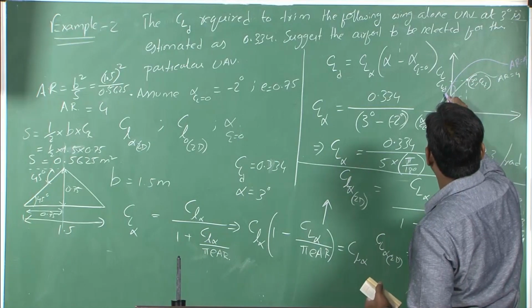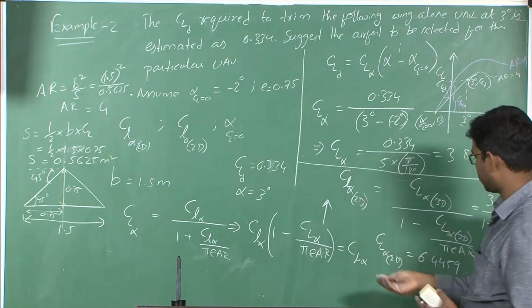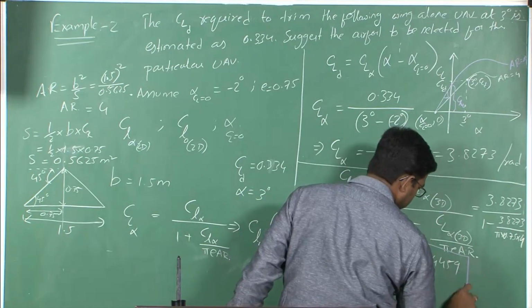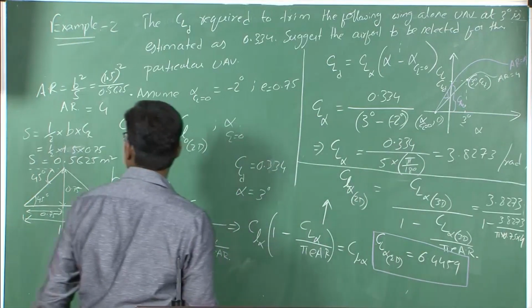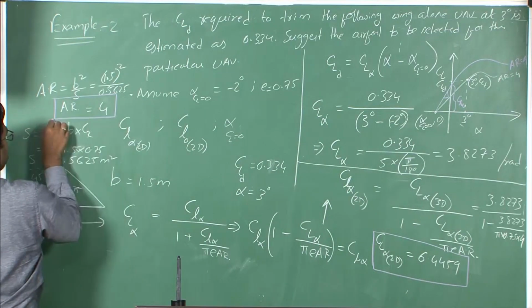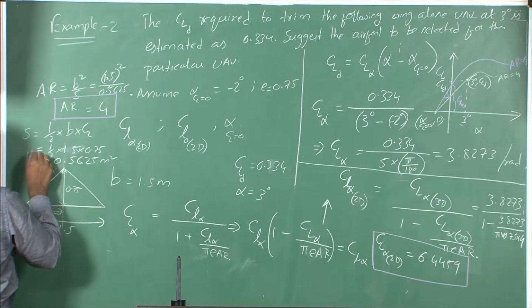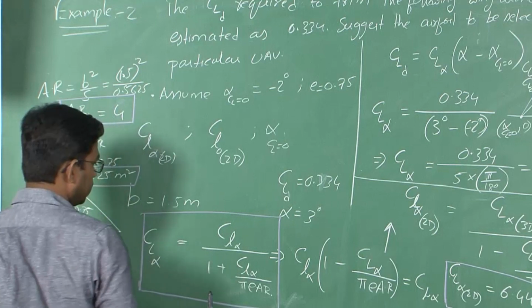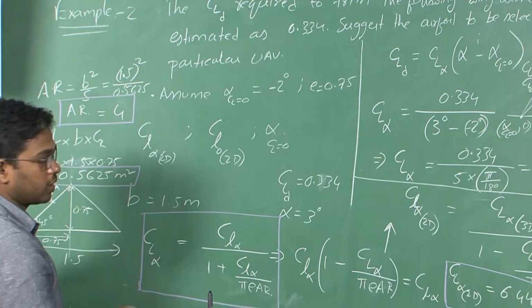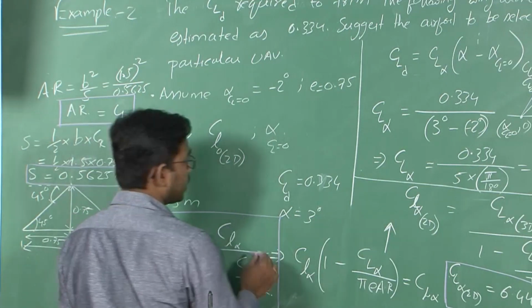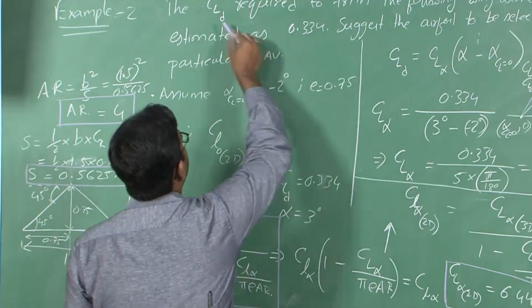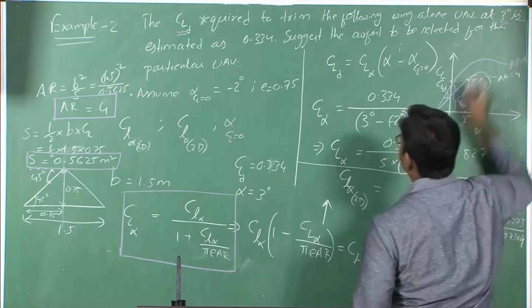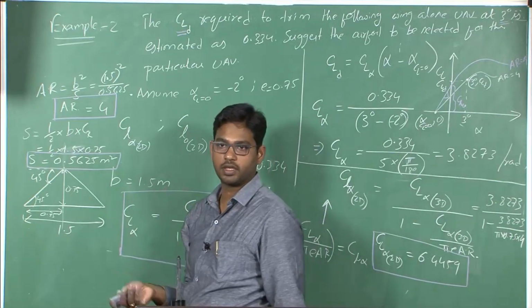We know the slope of this airfoil, just now we have figured it out as 0.4459. So we need aspect ratio to calculate that CL alpha. So we have figured out area from the given geometry. This is the relationship we started with for 2D CL alpha and 3D CL alpha. So we figured out 3D CL alpha based upon the design CL as well as the angle of attack at which this aircraft has to be trimmed, or that CL design has to be achieved.